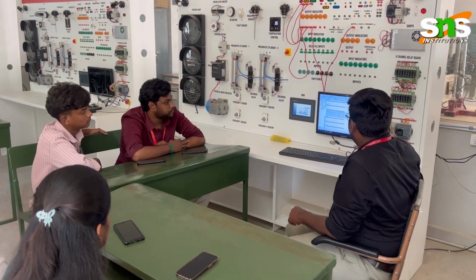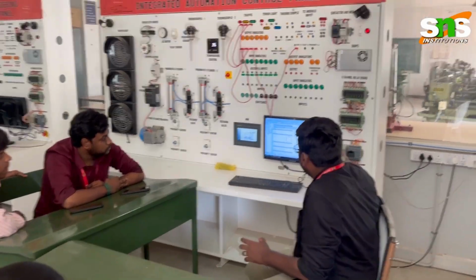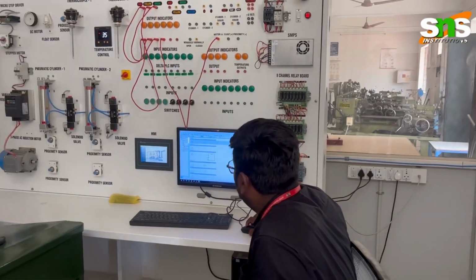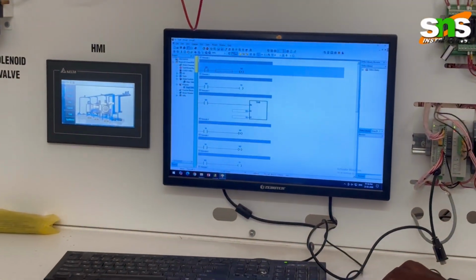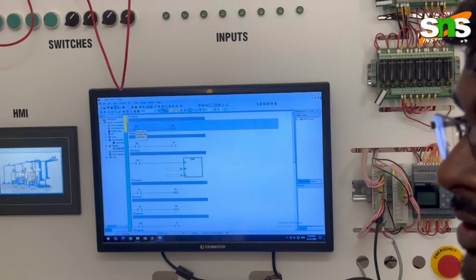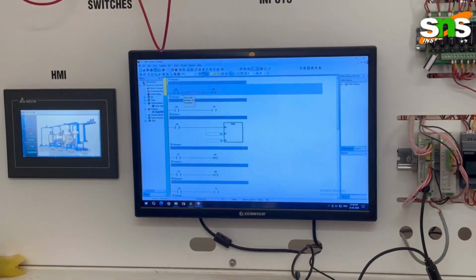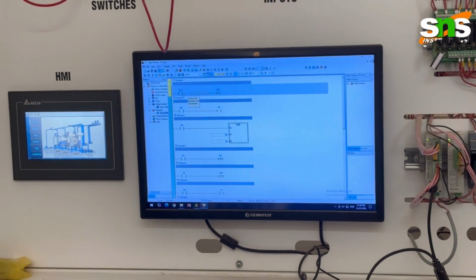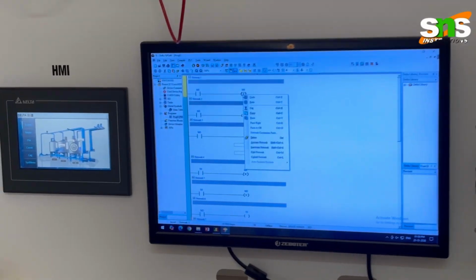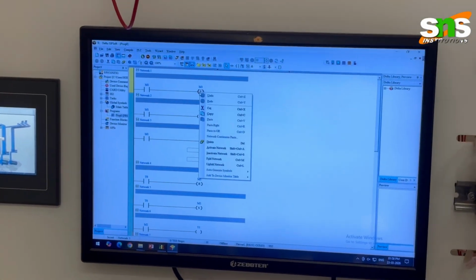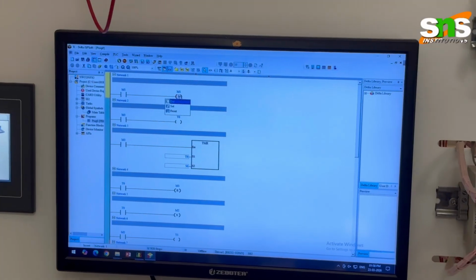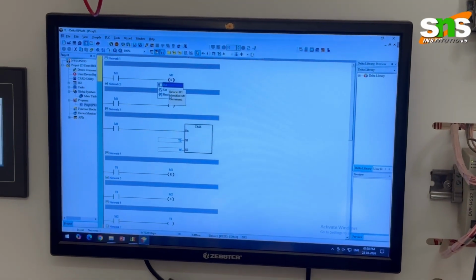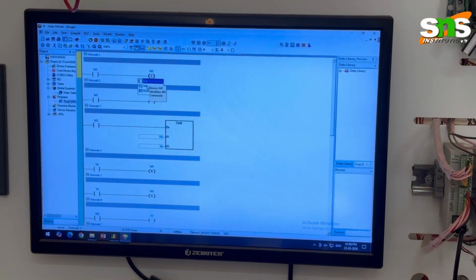Okay. So we can see the program. Firstly we open the normally open contact M1. M1 is nothing but a memory variable that acts as a virtual one. We have to set the preset value to set mode. It has three conditions: output, set and reset.